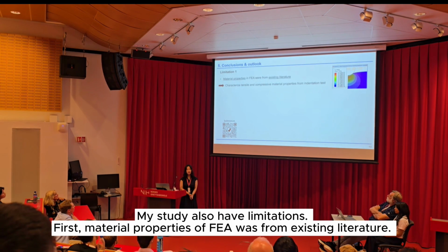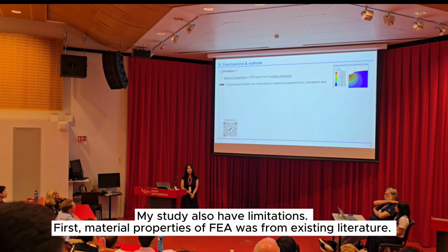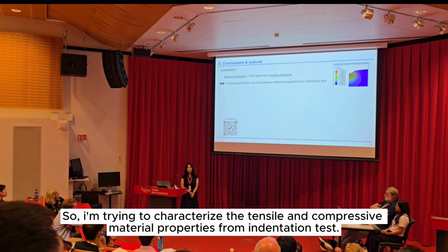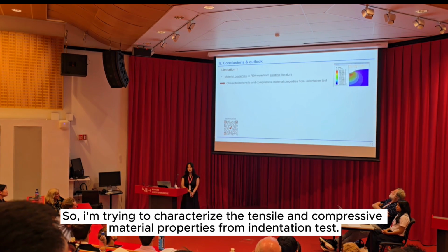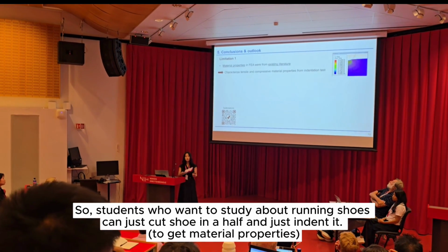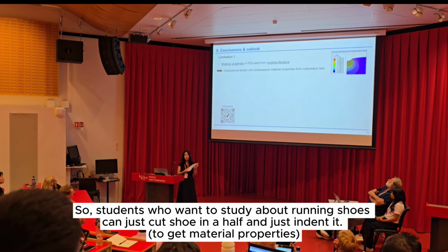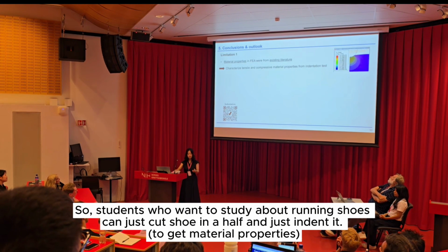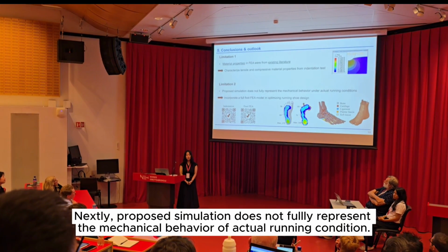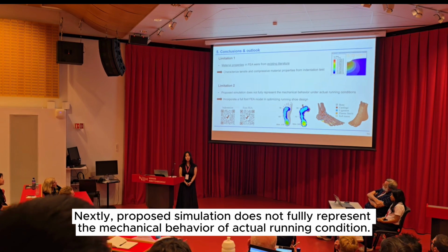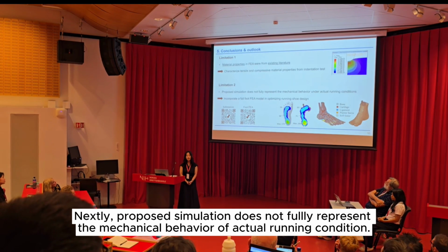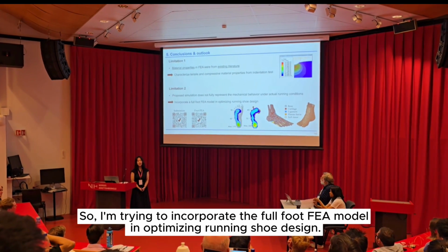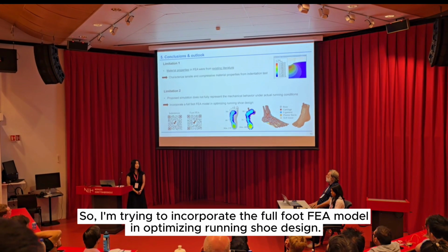My study has limitations. Firstly, the material properties in FEA were from existing literature, so I'm trying to characterize the tensile and compressive material properties from indentation tests. Students who want to study running shoes can just cut the shoe in half and indent it. Next, the proposed simulation does not fully represent the mechanical behavior under actual running conditions, so I'm trying to incorporate the full foot FEA model in optimizing running shoe design.